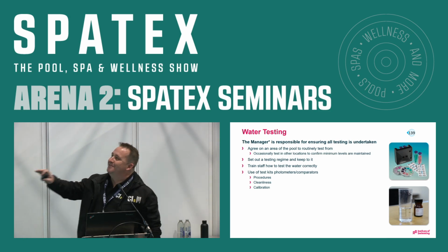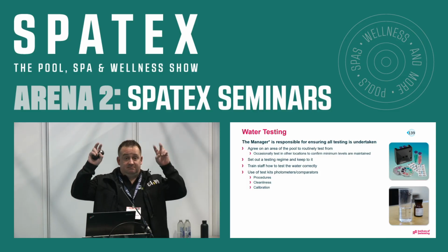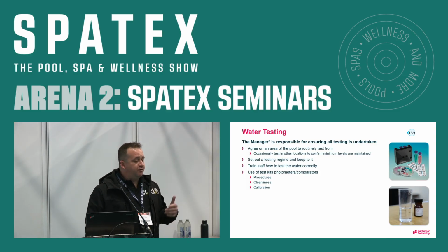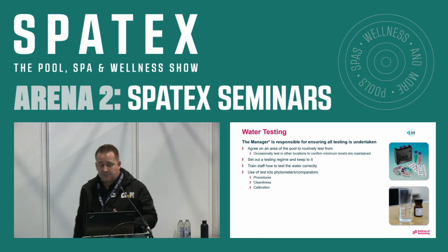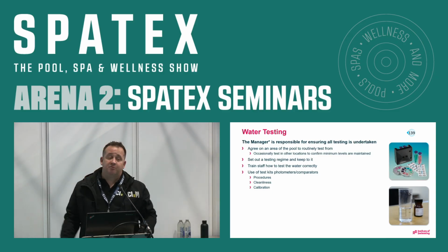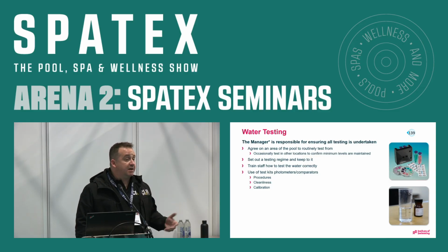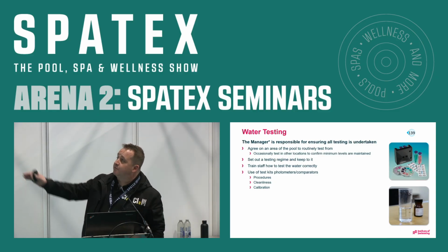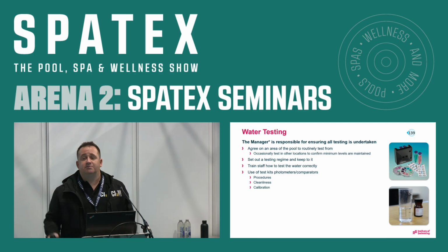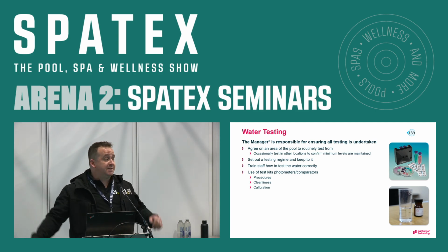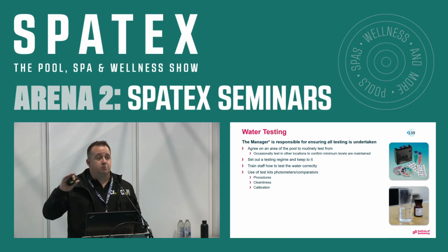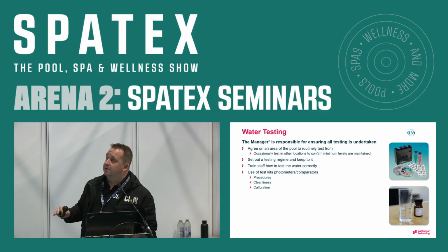Okay, the manager, in inverted commas, is responsible for the operation of the pool and ensuring that water testing is being done, okay? You need to set out your agreed area of pool where you're going to get the water samples from. Engineers will get very used to doing their water testing from the sample cell, maybe from the control unit, whereas the rest was taken from the pool. Set out your testing regime and stick to it, okay? Now, I'll talk about the PWTAG Code of Practice recommendations in a second, but you must stick to your regime, okay? There are no excuses for not following it.